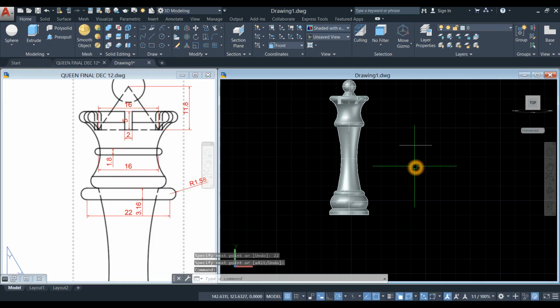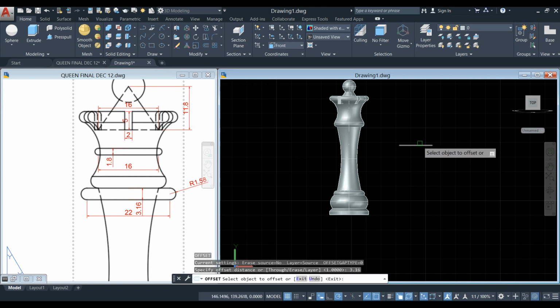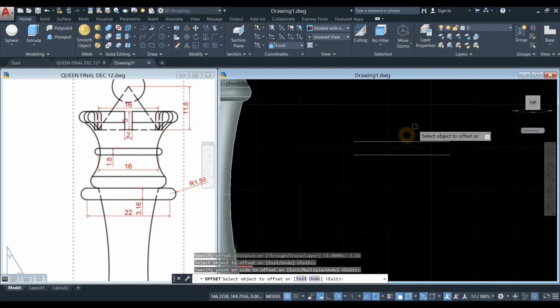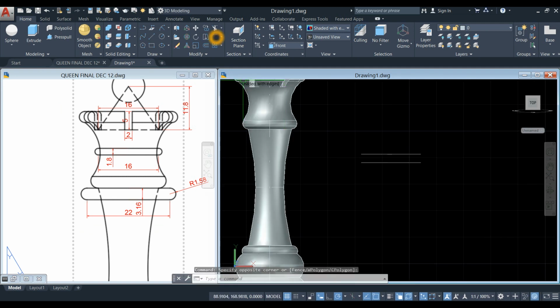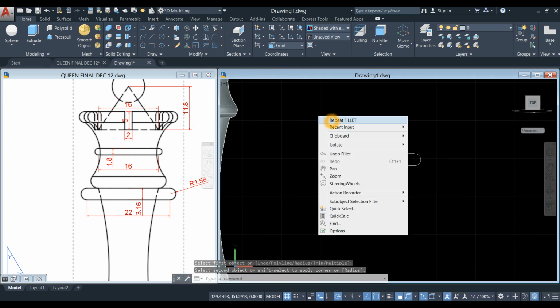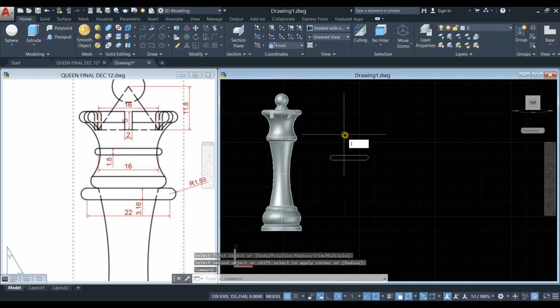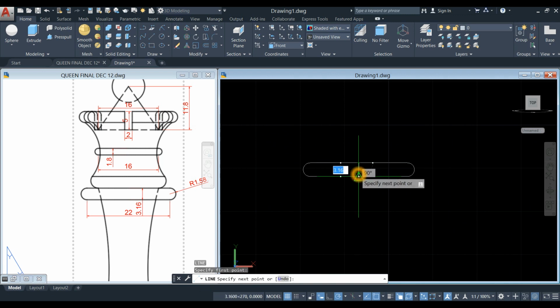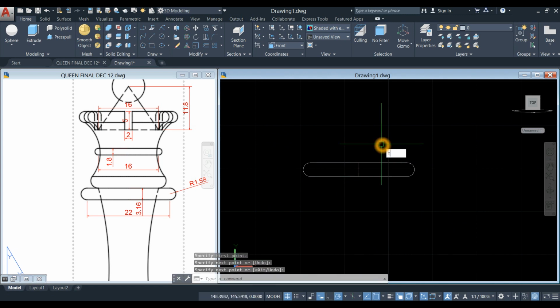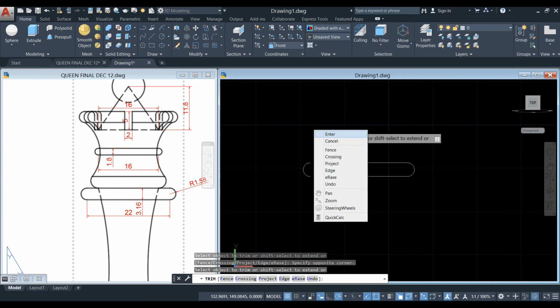And the thickness for that is 3.16 as shown here. So I'm just gonna offset, or for offset command, enter, and enter 3.16. Click this object or line, click above that line, and inside the modify panel, use the fillet command from the ribbon. Just click this one and click that. Right click to repeat fillet, click this line and this line, and draw a line from midpoint to midpoint. Type TR for trim command, enter twice, just remove that. Erase this one,